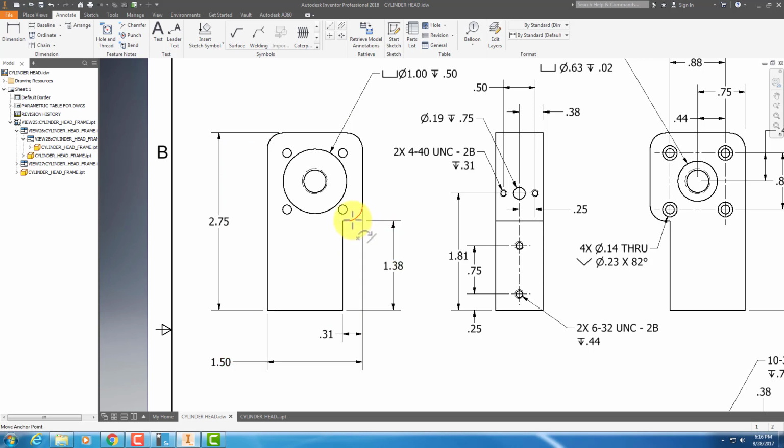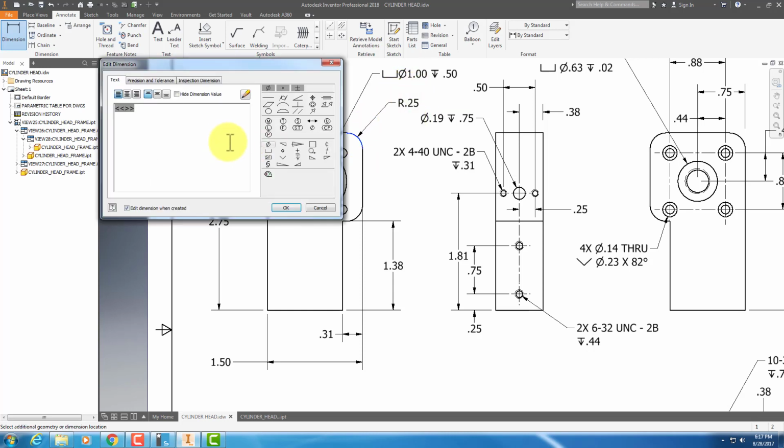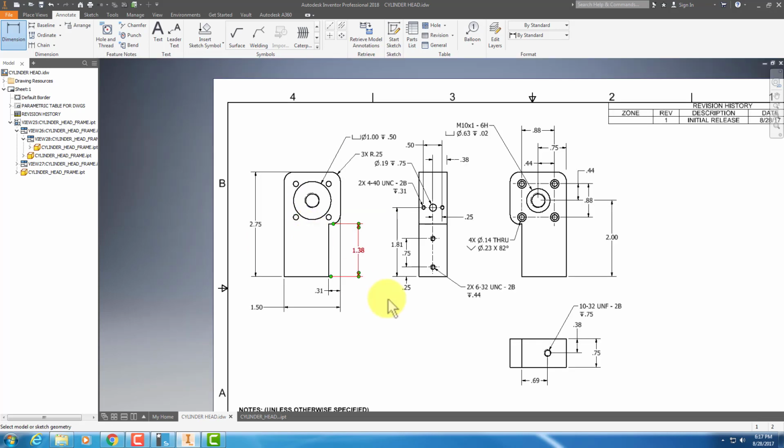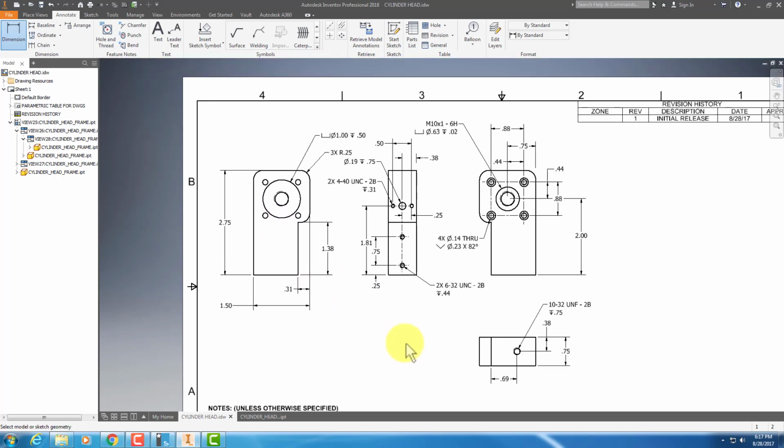It was correct in the first place, but now I've brought those fillets in. So now I can just put in a dimension for my fillets if I want to. Do not let it touch the center point. If it touches the center point, it thinks you want an XY dimension. Point-to-point dimension. So in this one, I'm going to go to home and put a 4x in here, or I'm sorry, 3x, and say OK. And so now I have all the dimensions in my part.